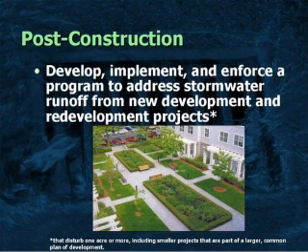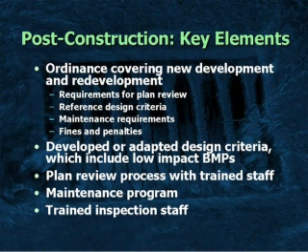Thank you, John. We're moving through this very quickly. Post-construction, as we've said in a couple of these webcasts, is probably the most challenging of all the minimum measures for many of the MS4s out there to get their hands around. And the basic element here, again, is that you need a program to develop, implement, and enforce the implementation of permanent stormwater controls on any new development or redevelopment projects. And similar to what John said, of course, that's on the 1 acre or more common plan of development kind of thing. So some of the basic elements there are the ordinance.